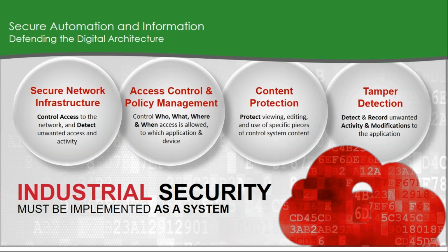You have content protection. Again, that's something that Rockwell's done a lot of work with on our later controllers now, to protect your IP so that you can lock that down and no one can pull it out of the controller. And then tamper detection. So making sure that our controllers have firmware in them that can't be spoofed, and our digitally signed firmware.